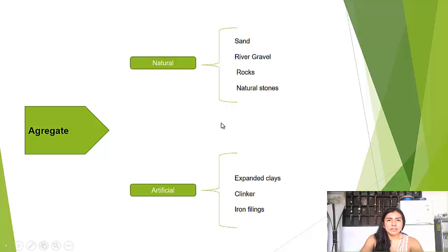Today, concrete that has recycled material is mostly used in non-structural applications because the quality of the aggregates influences the mechanical strength, and therefore leads to expansion, cracking and low bond strength. It is for this reason that tests are carried out to determine this resistance, and from the results to promote a structural use of concrete with recycled material.